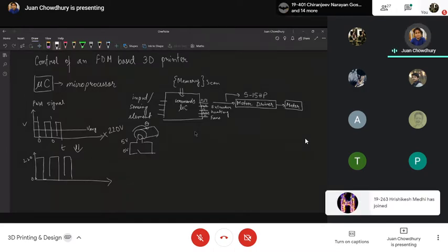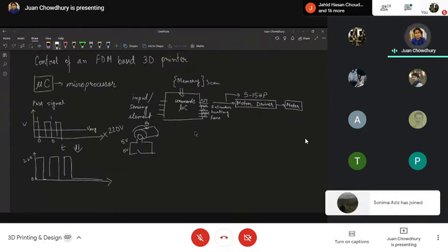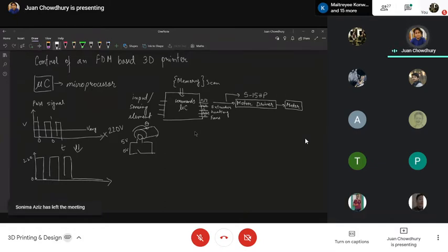All right. So whenever there is an interrupt by the input surfaces, say that relay switch that I recently marked in red, that has been kicked off, it will override these commands and cut off the PWM signal so that there is no motion of the motor in the X stage. So this is one elemental form of operation, how a microprocessor controls 3D printers in particular, or any system that has motion in general. This is how a microprocessor controls.